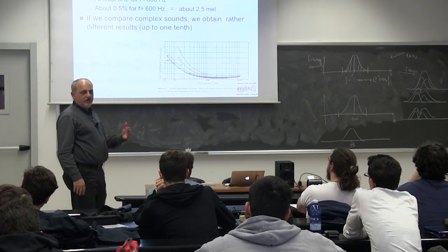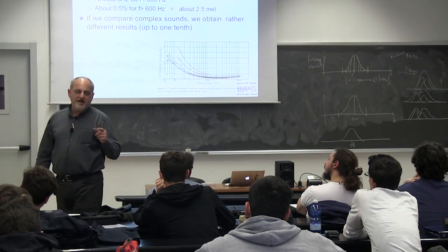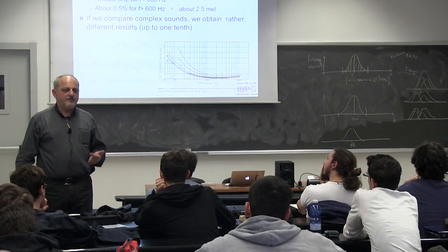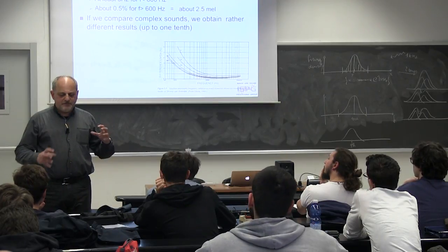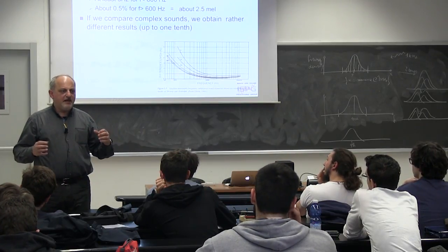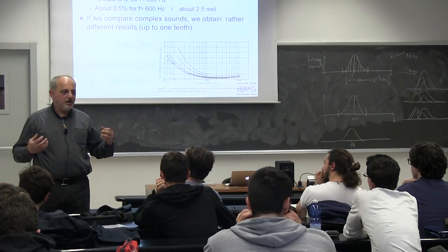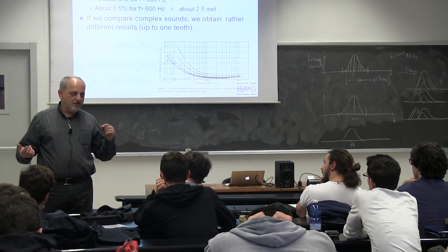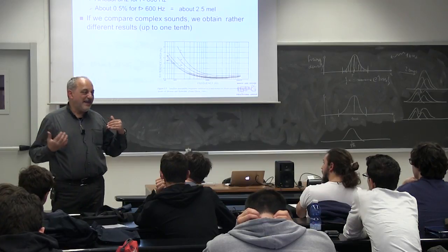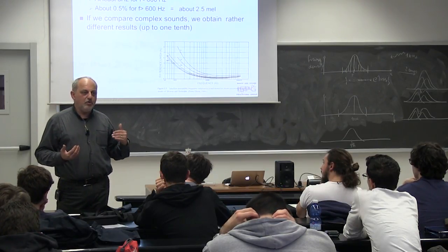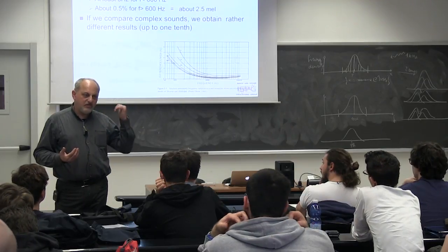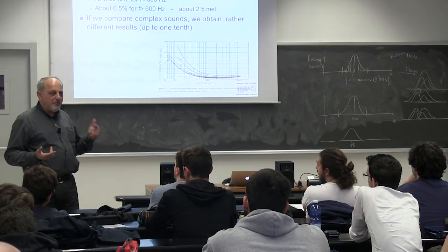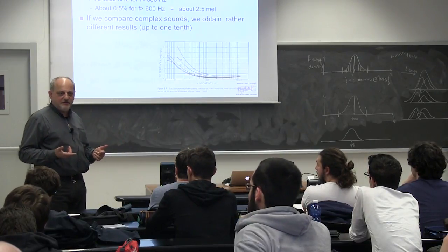You might think that this is not very useful right now, but you will find that you need it for designing systems that perform frequency analysis. You want to design the length of the filter, the length of the window, the length of the FFT in relation to the window, in order to have an error of localization of peaks that is below audibility. In that case, you have to know the JND. So I'm telling you a bunch of things, but believe me, remember them, because otherwise you won't be able to design systems later on.